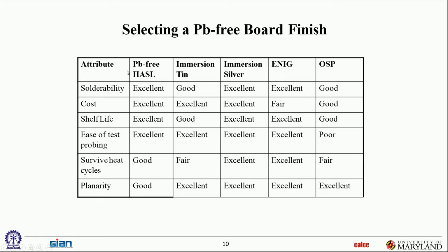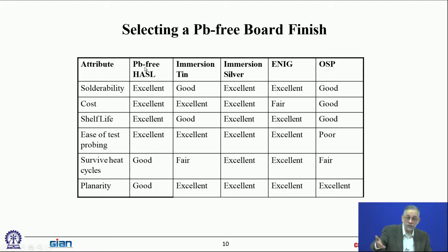So as an example, when you put tin solder finish on your boards, you actually have to go through a leveling step. HASL stands for hot air solder leveling. So it's actually leveled with hot air, otherwise you don't get good planarity after you solder plate all your pads. All right, and you can see some of them have come out with excellence everywhere. Some did not so good.